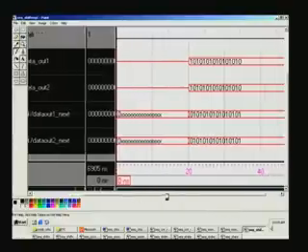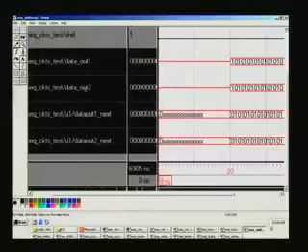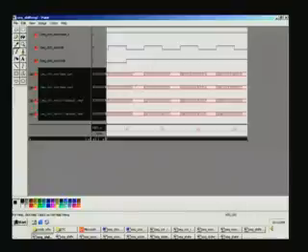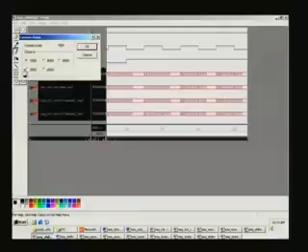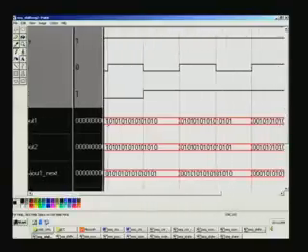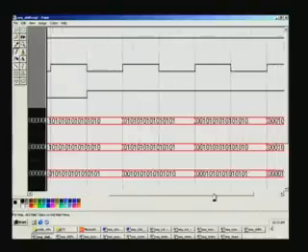If you have a look, you can see that data out 1 and data out 2 are exactly the same, because it is the same problem solved in two different ways, and this pattern will keep on shifting. It is there in the next two slides we can see. So, if I once again zoom this here, these are all the data out 1, data out 2. The first value was 1010, with the arrival of the next clock pulse it has become 0101, and both are same.